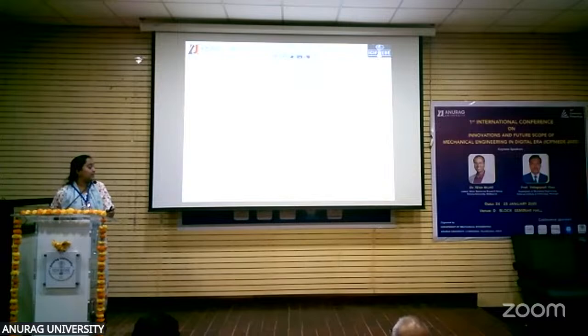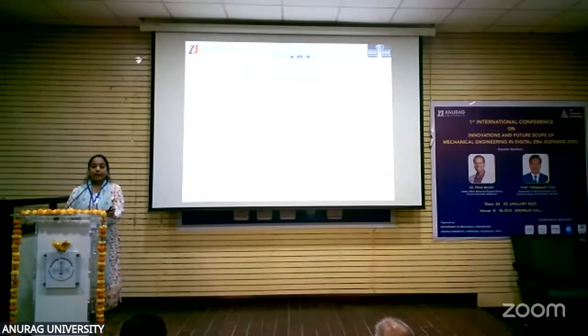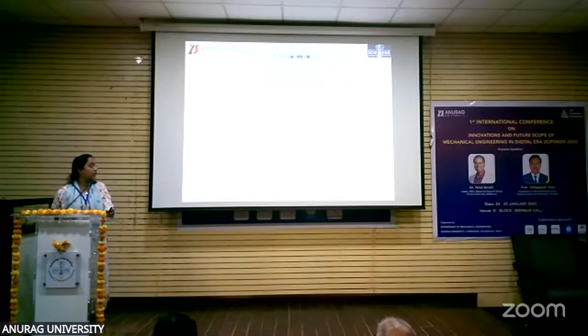So this is the analysis data for the different plastic materials we have taken. The weight is the same for each material, and then the amount of oil we have extracted. The temperature ranges are generally from 300 to 500 degrees Celsius. Coolant temperature is constantly maintained around 20 degrees. The runtime is around 100 to 130 minutes.